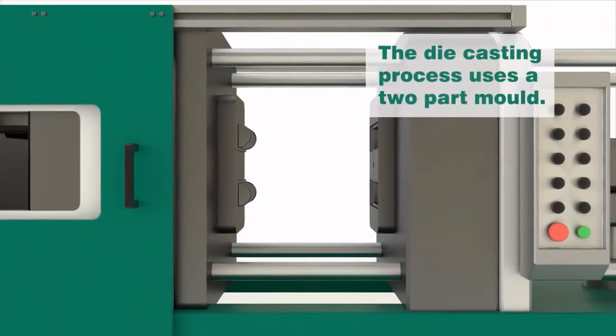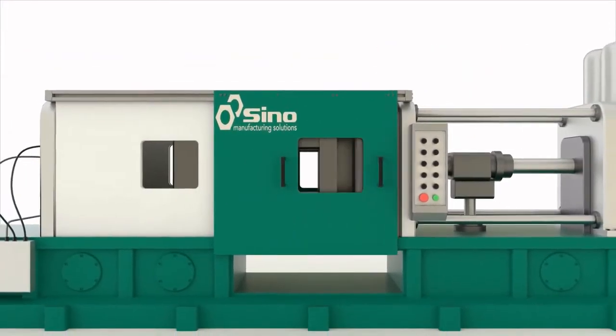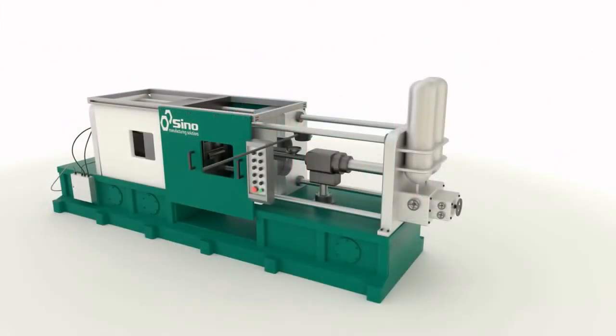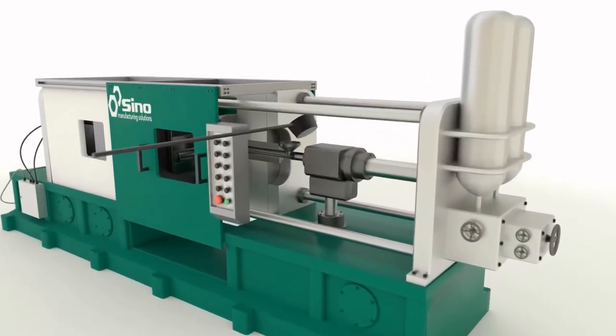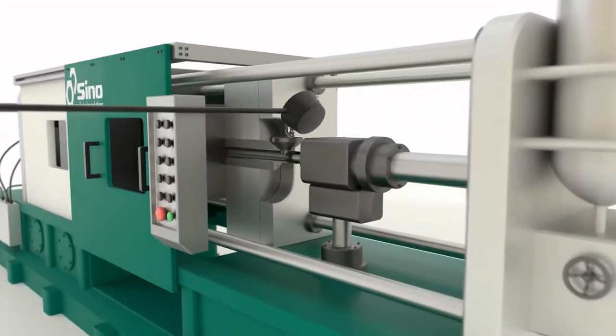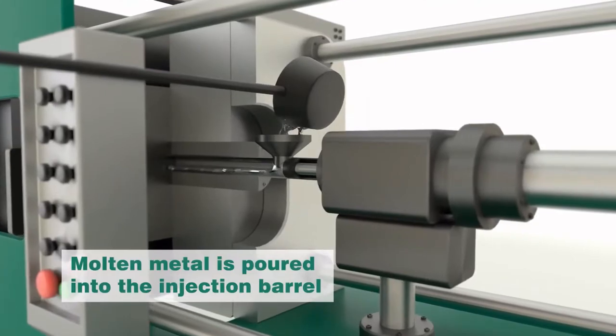Cold chamber die casting. In cold chamber die casting machines, molten metal is poured into an unheated chamber from an external melting container, and a piston is used to inject the metal under high pressure into the die cavity. Injecting pressure may vary from 14 to 140 megapascals.